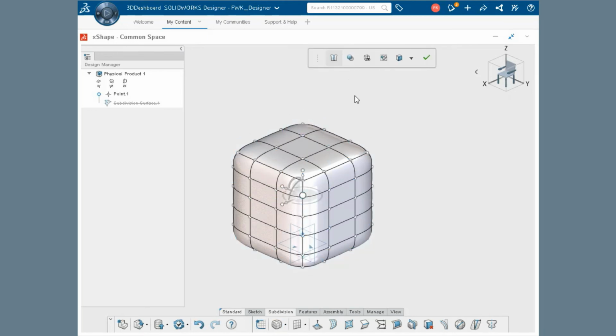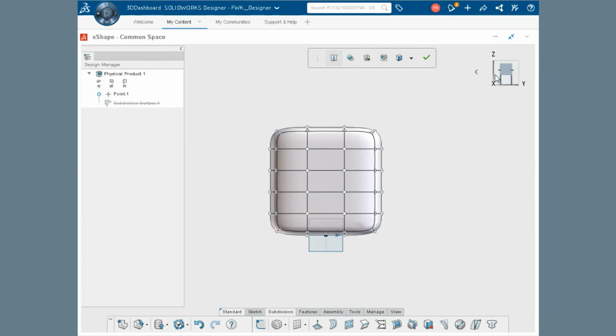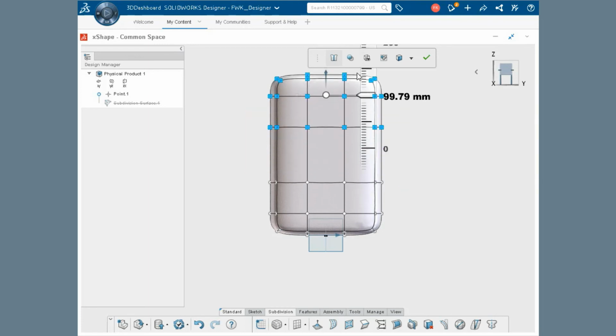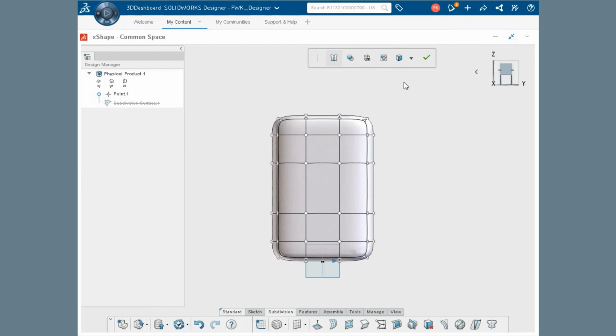Let's start with the changes right away, those changes that do not require the symmetry tool. Change to the front view, box select the upper vertices, and pull upwards about 100 mm, and again click Air. This bottle has an angled top, so I'll select the top left couple of rows of vertices, not the whole top. Using the Arc tool, rotate the vertices about 20 degrees counterclockwise.